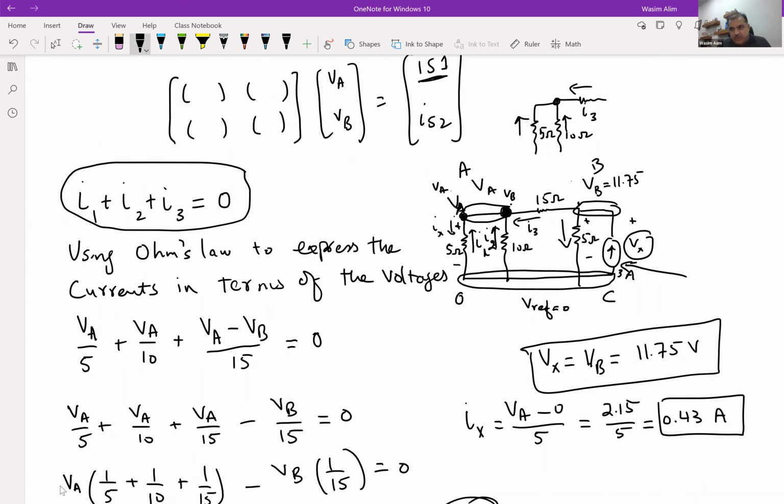So that's a good starting point, right? And you have the flexibility to write the currents in any direction that you want, as long as they are consistent across the entire set of equations. Over here, I chose this direction to go the other way, but I could have chosen it to go up also. Whatever direction I choose here will not have impact on the first equation because it's not part of that first equation.